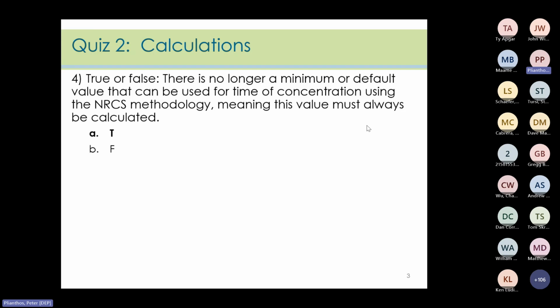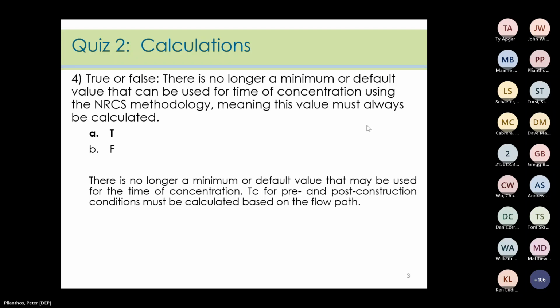And that is true. There is no longer a minimum or default value that may be used for the time of concentration. Time of concentration, or T sub C, for pre- and post-construction conditions must be calculated based on the flow path.